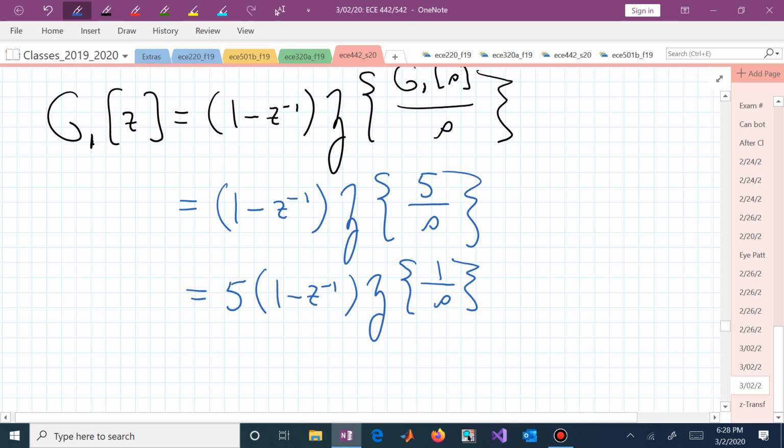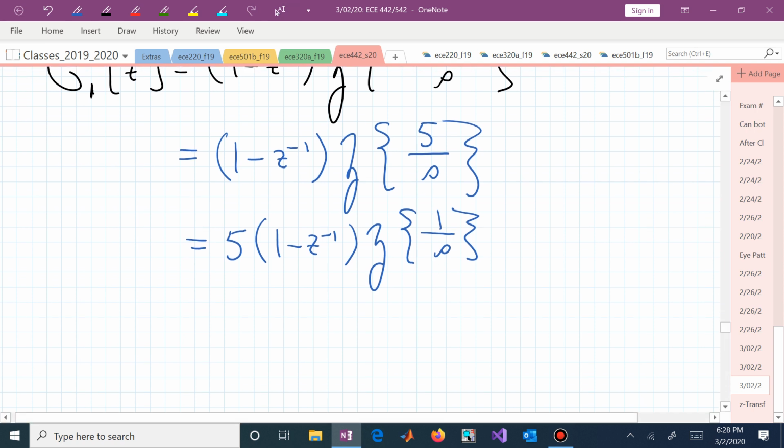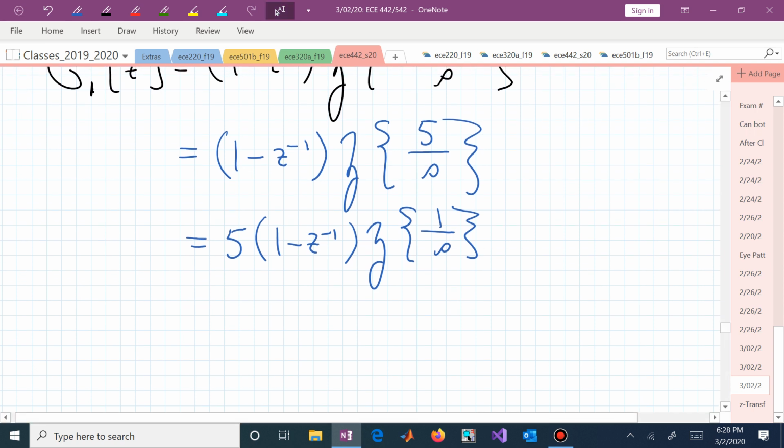And you actually might see a table that has the Z transform of 1 over S. Boom, now you just plug that in. But in fact, what did we say is going on behind the scenes? We have to inverse Laplace transform that, sample it, and then Z transform that sampled signal.